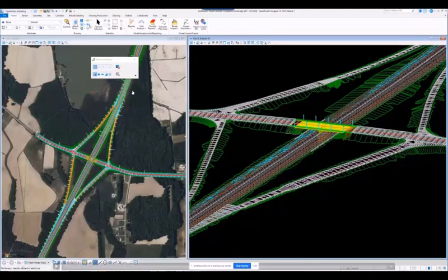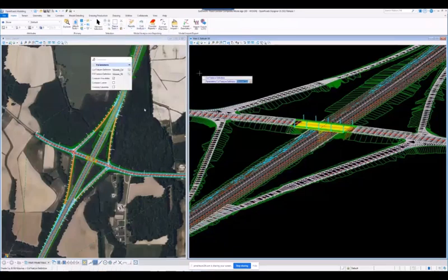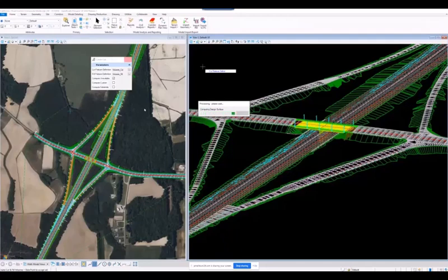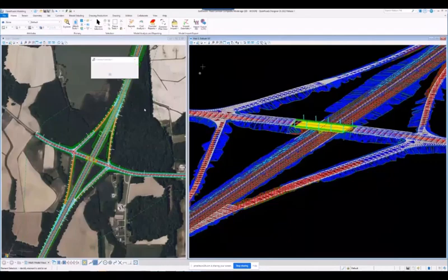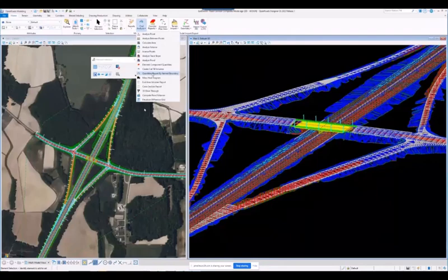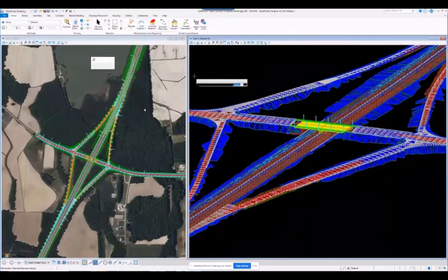So basically at this point, I could just go in here and run cut fill. The software knows what you made. It analyzes the three-dimensional model, looks at that mesh, and determines what it is. Is it unsuitable? Is it design? Is it existing? You put all that effort in your standards in your model. Software should know about this stuff. It should be almost automatic. You did all the hard work with modeling. So with that, it was able to establish the cut and the fill represented between your design and existing.